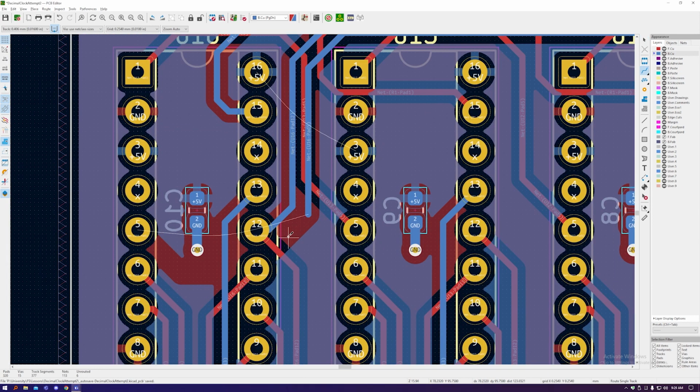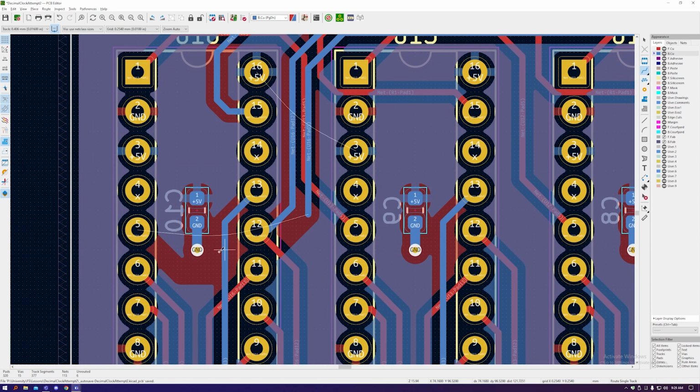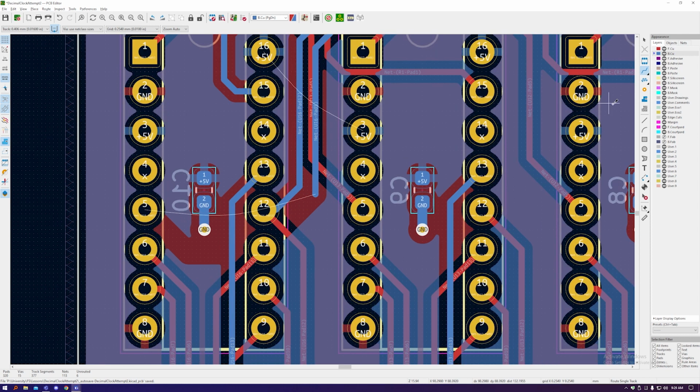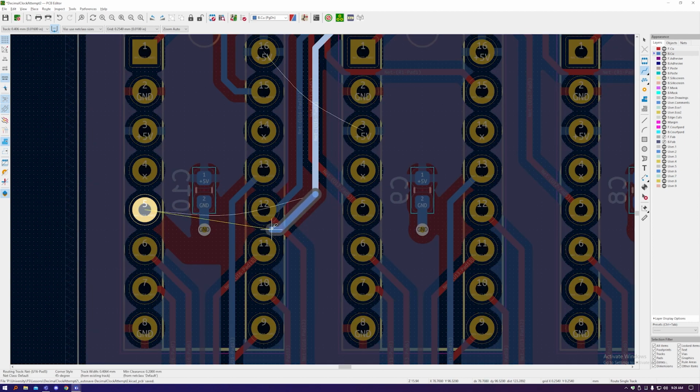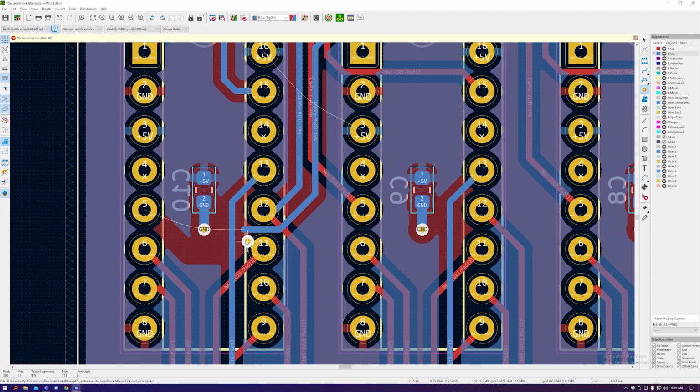So this looks like somewhere where we might need a via. You can see blue would still be good to cross over here, but then we need red to cross over this one that we've just fixed. So you can see a via might fit there, or it might go there. I think we'll probably put it here and move this blue one if we need to. So let's go blue trace, and I'll explain what a via does. Let's see if we can pop one there. No.